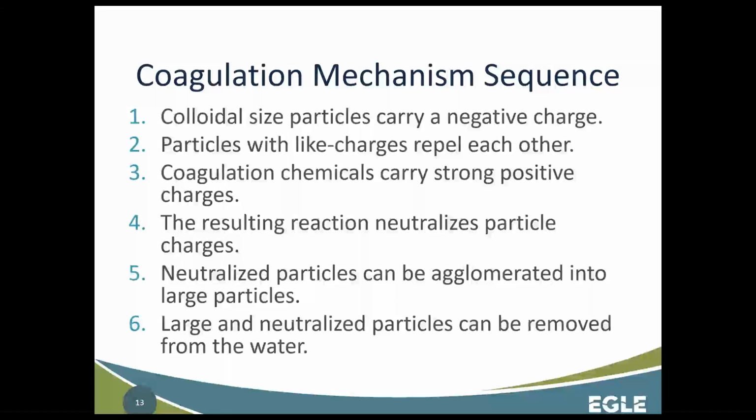These large particles are much easier to remove from the water, and that can either be from settling or from applying it directly to the filter. And we're going to want a different type of floc if we're trying to settle it versus if we're going to put it directly onto the filter. When you're settling it, the big, large sweep floc is going to drop out of the water column faster than a smaller pin floc.